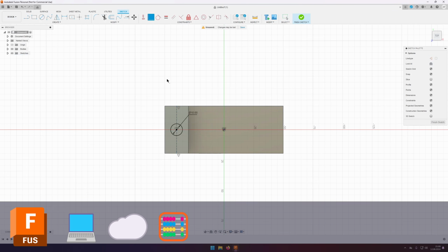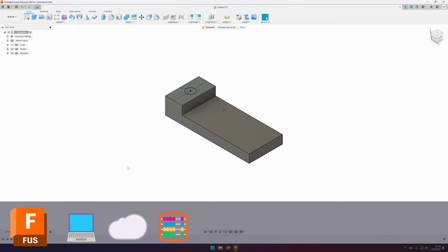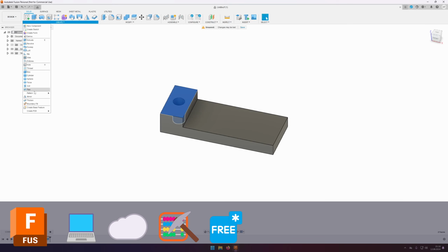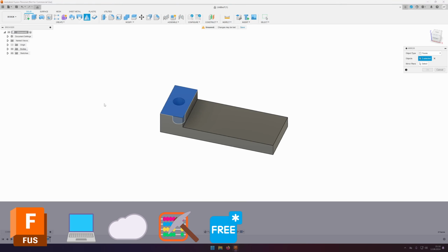However, Fusion keeps up with modern times and demands, so it introduces direct modeling functionality as well, which means that you will be able to move features, offset, or even delete faces. Fusion is free for personal use, but you will be limited to 10 active projects. That means that you can have more projects, but you will need to manage them, disable some to create new.